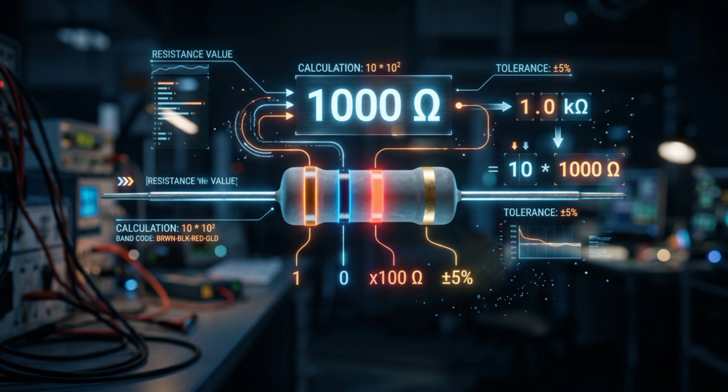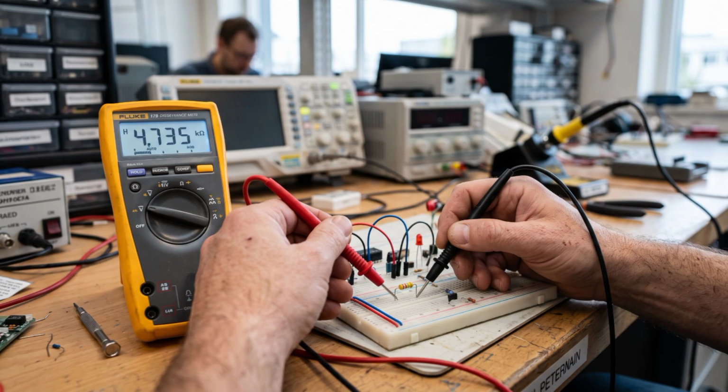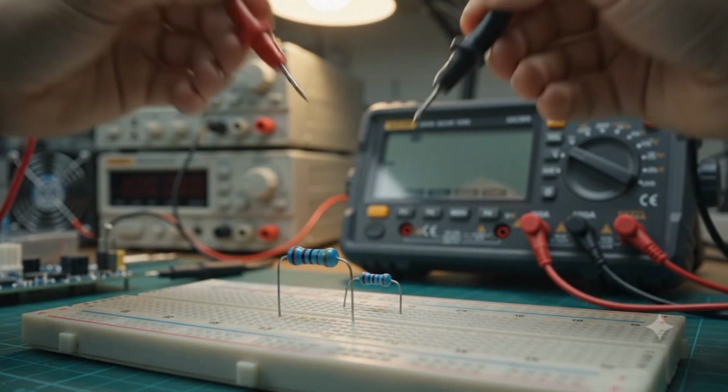But here's where beginners get confused. 5-band resistors exist too, and they are used for higher precision circuits like medical devices and computers. But engineers rarely rely only on color codes. They use a multimeter. Set it to resistance mode, place the probes on both ends, and the value appears instantly.